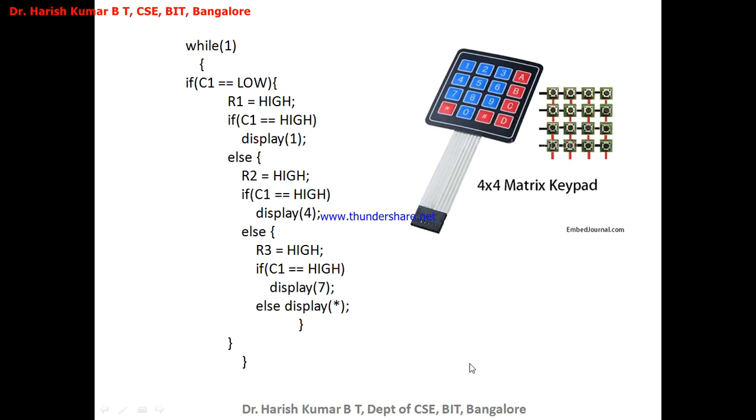Yeah, and the implementation, I was telling, is software. It is just the keypad which is connected to the microprocessor, the controller. When I press some button, how is it going to take the value associated with that button? We are not going to store this value inside the button. It is just a switch. Now if I press this switch, the software will say it is the value 5. Now how? See, I have an infinite loop. This will be running in an infinite loop.